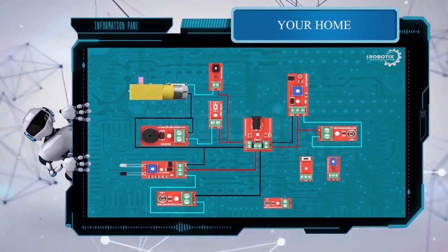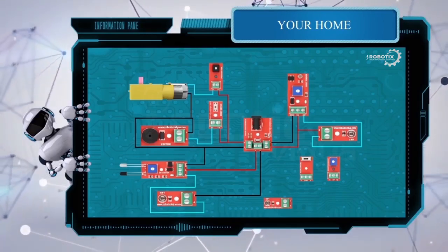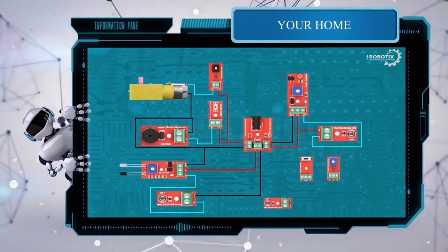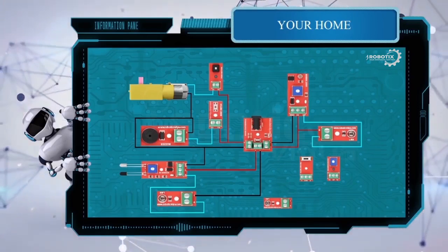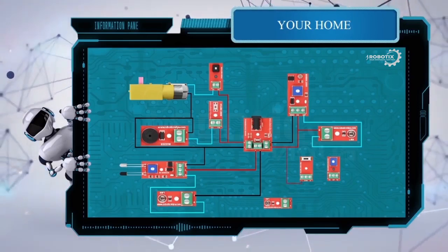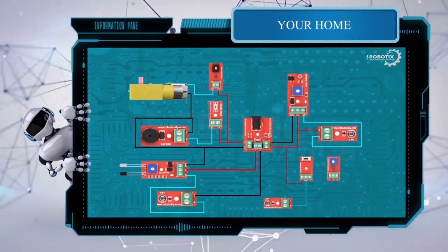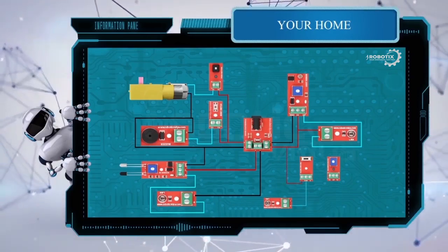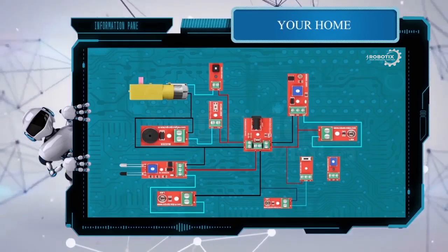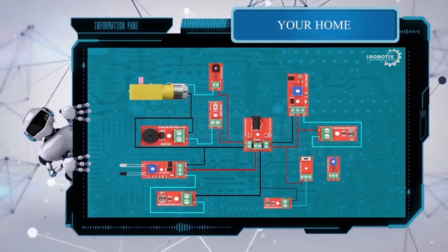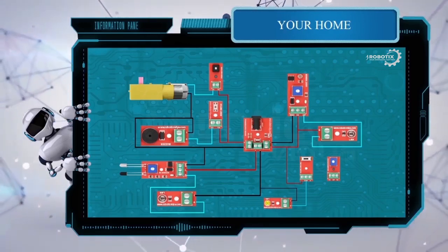Now before we go into the connections, you will have to understand that when the LED is given the supply directly, the LED will glow in full brightness. For that, connect the positive of your power supply board directly to the terminal A of your two-way switch. Now, the common of your two-way switch should be connected to the positive of your LED, and the negative of the LED will go to the power supply board's negative.